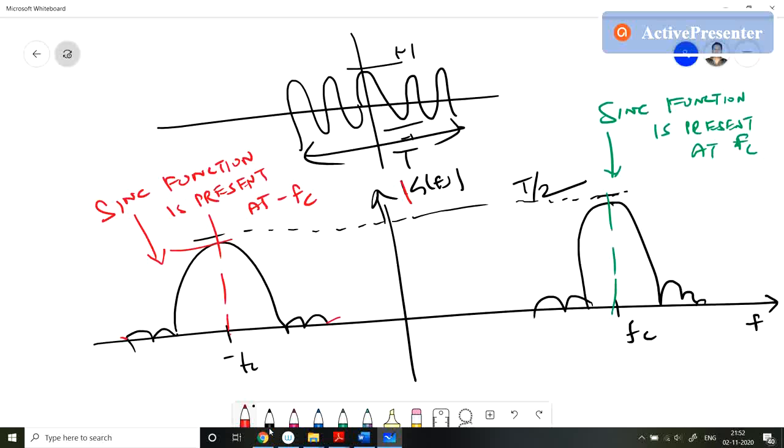That's why the negative lobes of this sinc function become positive, because we have taken the modulus here. So every negative area will become a positive area. And of course the sinc function is basically a decreasing type, but it is an energy signal. Why is it an energy signal? Because it is bounded. When f tends to infinity, it is 0.